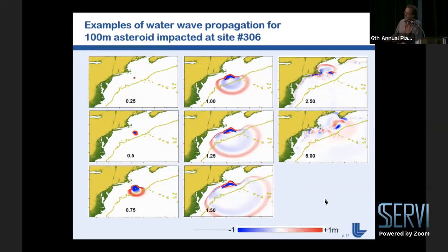Here it is 100 meter. No, it's on top of the continental shelf. And I did not do these in the linear model because you have to do them in nonlinear hydrodynamics, so I had to switch back, because there is not enough water depth. If you use just a shot right there, you will dewater the ocean. So I had to run them all in the nonlinear regime, and I will show you the results. But again, you see the resonance.